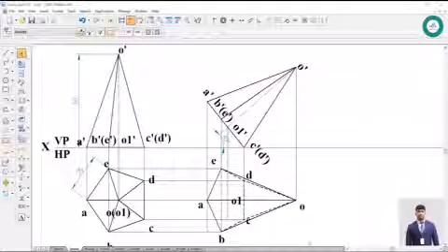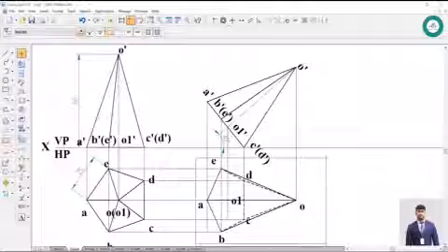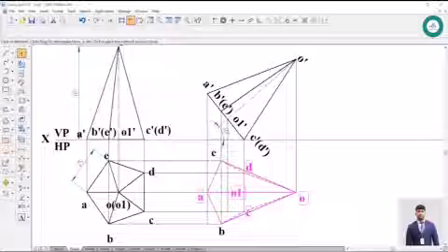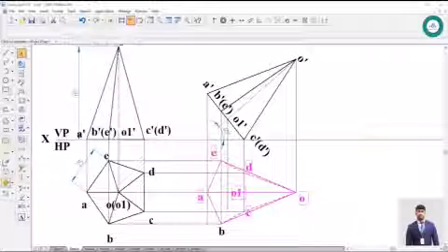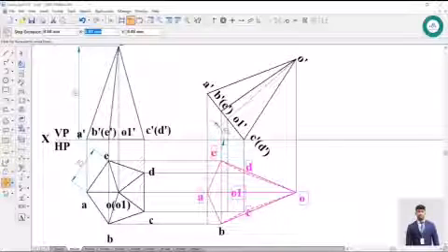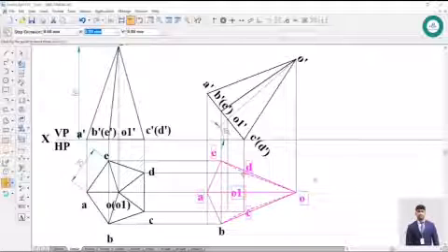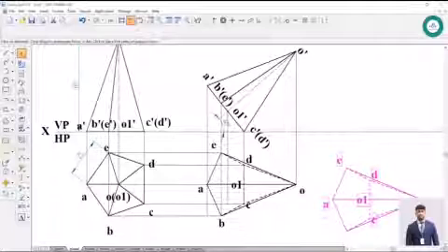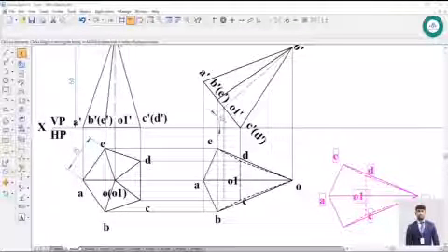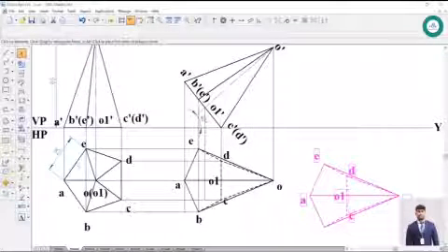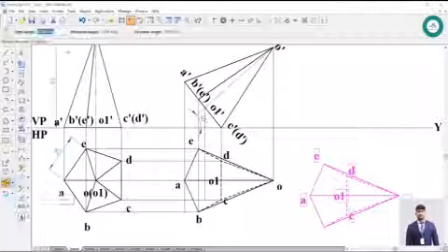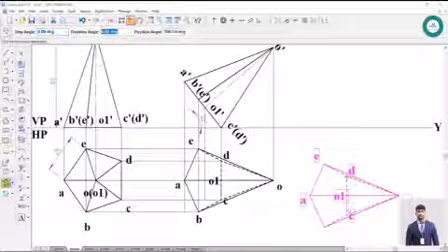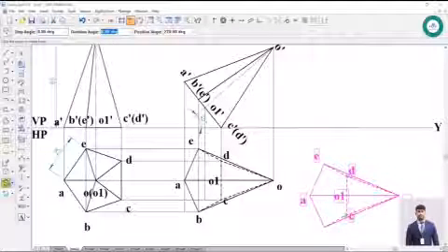Further, select this particular view, including naming. Go to move command, switch on the copy, click with one point and place somewhere here. So after placing, go to rotate command. So click this point, and next is a lower point.